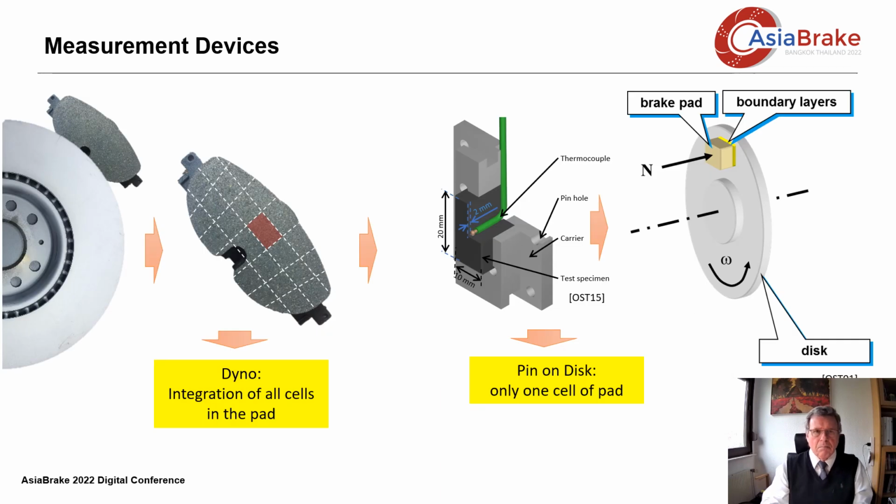If you test and measure a complete brake, then you must take into account that the pressure, temperature, and friction conditions over the brake lining vary very strongly in time and place during a brake application. However, wear and the generation of emission particles depend very much on these variables.